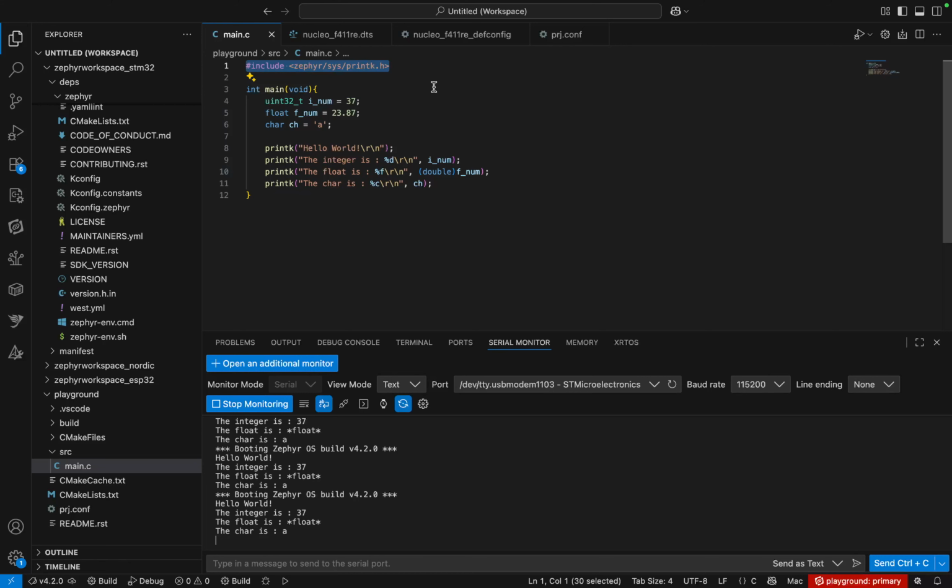Having said this, I'm going to say one more thing. The printk function is an in-place logging technique. What it means is that it can have negative timing effects on your firmware. Whenever your MCU encounters a printk, it is not going to execute what comes after it until the printk function has finished. And remember, this is a write operation. It is writing over a communication channel. And these are some of the bottlenecks in programs, right? So until all the bytes have been written to the UART peripheral, your program is not going to continue. And this is what makes it bad.